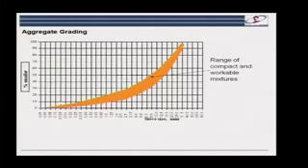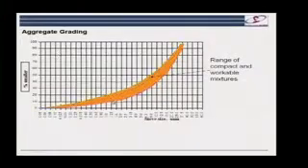And you have a basic knowledge which has been built up by experiment, which tells you that if your aggregates have a grading which is in this kind of orange zone, this is a good zone for compact and workable mixtures. Okay, so we can see here that the size of the aggregates is on a log scale. So you see in this example, we're going over 3 orders of magnitude from aggregate size well below 1 millimeter up to about 80 millimeters or so. Typically, maybe for common concrete like it's used for building these walls, the cutoff point would be about 32 millimeters.